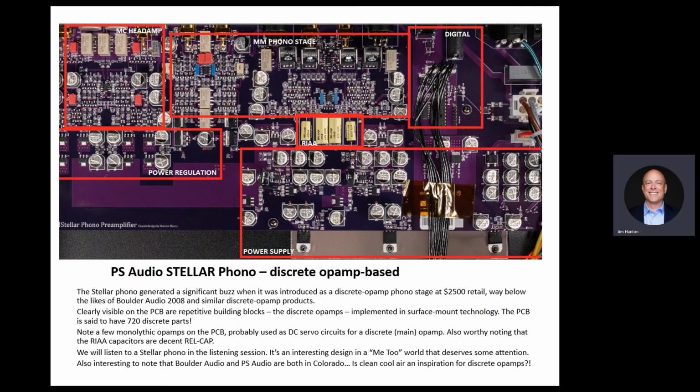And then you have a standard circuit. You have the moving coil input stage, super low noise. And then you have the standard moving magnet phono stage, the two-stage design. And you have an RIAA with reasonable size capacitors, okay? I would say the quality of capacitors in the RIAA here exceeds the Boulder 2008. So I think the guy basically designed, you don't think?